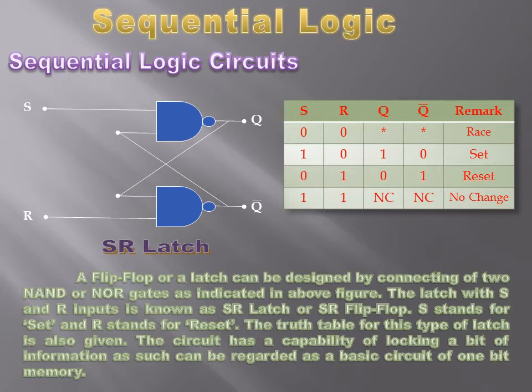So this is an SR latch, or we call it an SR flip-flop. This latch is considered a circuit which can latch one bit of information, one binary bit of information.